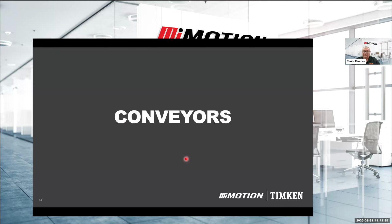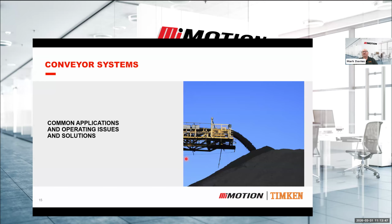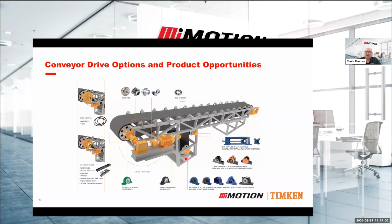So in conveyor systems, once we usually go through a crushing stage, we're now able to actually move the product around on conveyors. And bulk handling conveyors is what we're talking about today. Also commonly known as trough conveyors, because the product doesn't sit on a flat belt; it sits on a trough. So the standard layout for a conveyor, you've got a single direction of travel.